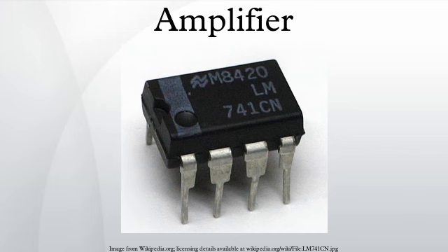Some feedback, which may be positive or negative, is unavoidable and often undesirable, introduced, for example, by parasitic elements such as the inherent capacitance between input and output of a device such as a transistor and capacitive coupling due to external wiring. Excessive frequency-dependent positive feedback may cause what is expected to be an amplifier to become an oscillator. Linear unilateral and bilateral amplifiers can be represented as two-port networks.